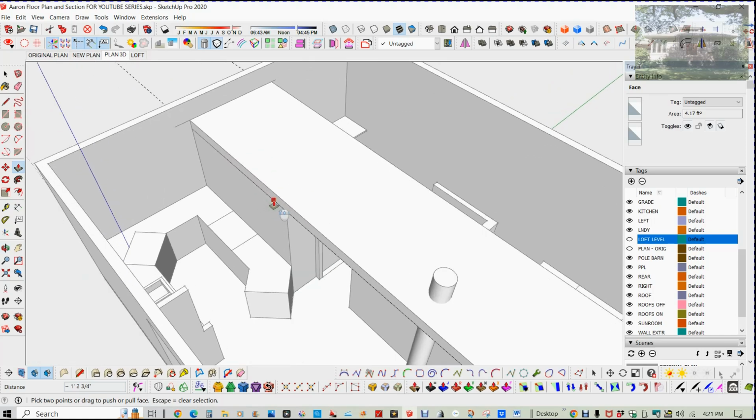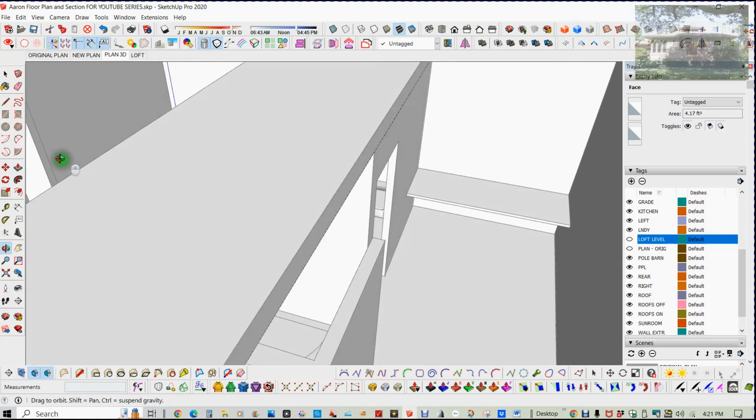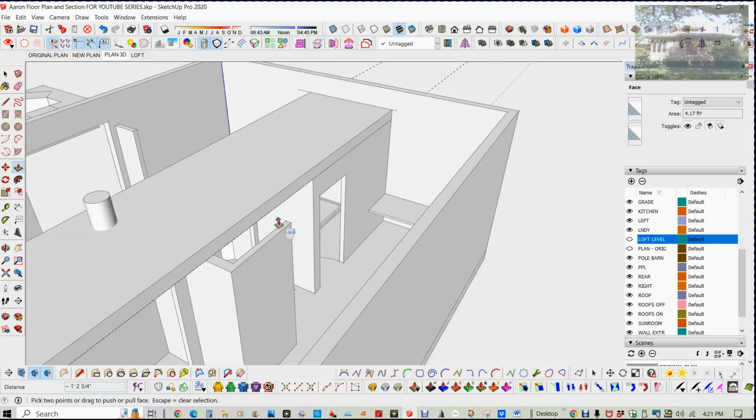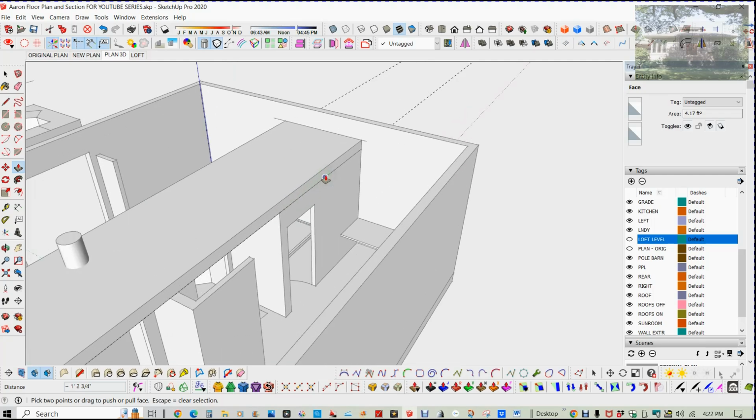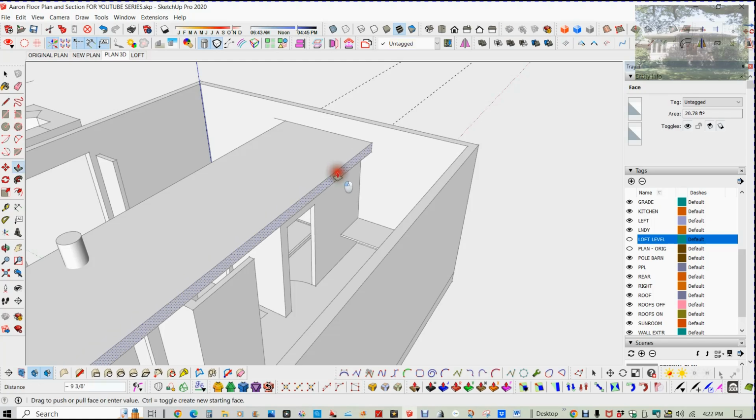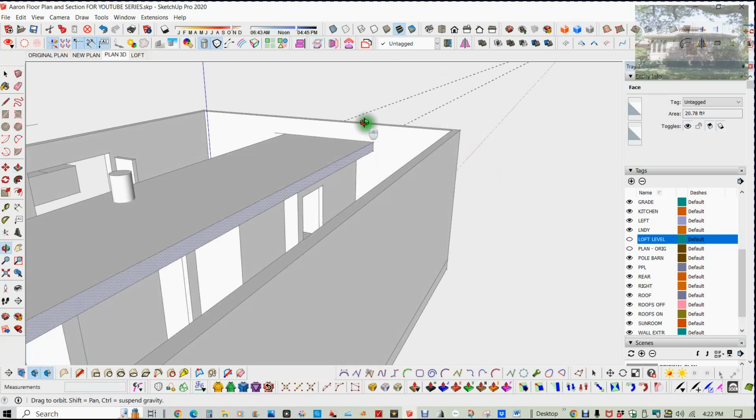The restroom has the mechanical space on top of it, which you can see here right now. What I want to do is have lighting ledges, plant ledges, if you will. It's going to have vaulted ceilings in this building, so lighting is going to be something I have to pay attention to. So I do a lot of uplighting, which is recessed lighting in the tops of soffits instead of in the bottoms, sometimes both. We'll pull this out. The lights are 6 inches, so we'll go 16. I'm just pulling that out 16 inches so we have a soffit.